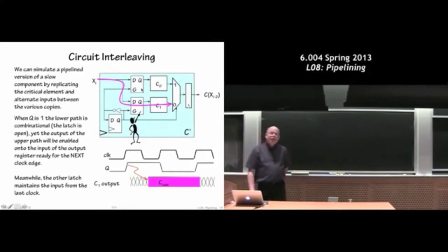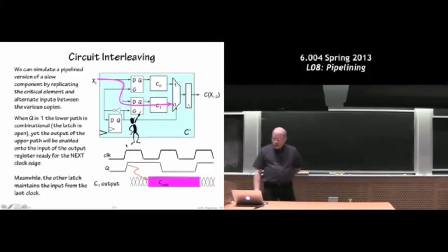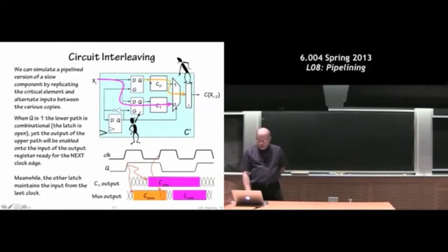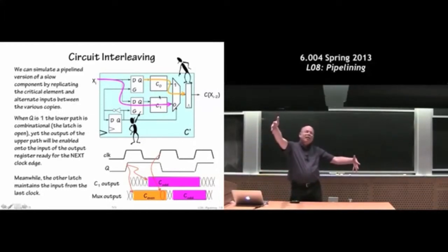The idea is that we're going to actually interleave these 2 C components. So on a particular clock edge, we're going to start the processing of 1 component while the second component is finishing from the previous cycle. So we're starting a new one, which must mean at the end of the current clock cycle, the other one is going to be finishing up.